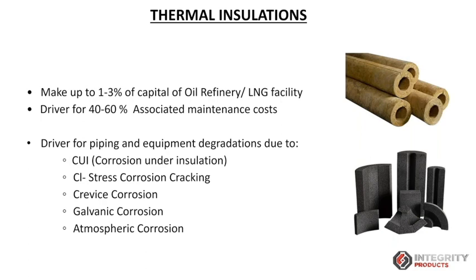There are a few facts about thermal insulation: it can make up to 1 to 3% of the capital cost of the facility. We know there is a high-cost investment in pressure vessels, gas turbines, steam turbines. Sometimes we think insulation is a very low-cost item. But since it's bulk in numbers and there are associated challenges, it can make up to 1 to 3% of the capital cost. And as I mentioned earlier, it's a driver for 40 to 60% of piping failures.